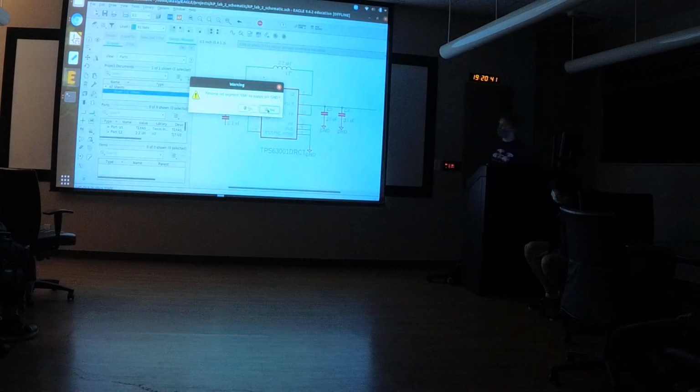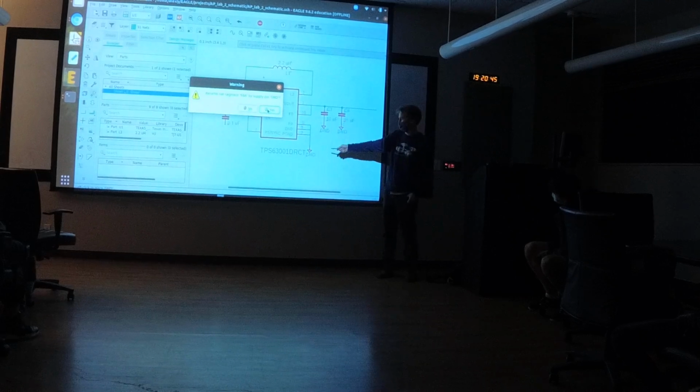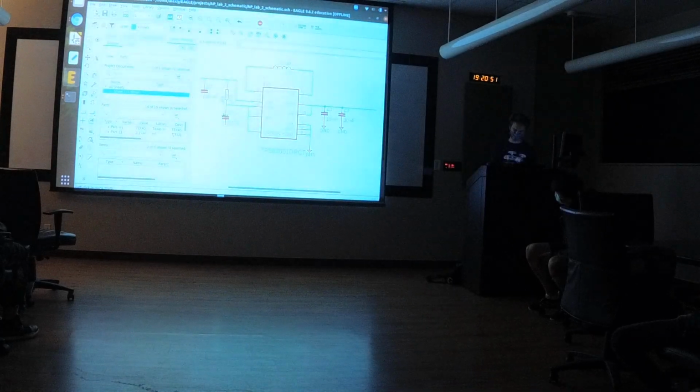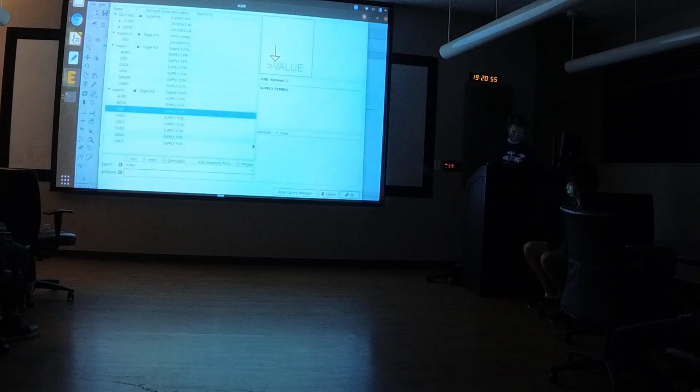It's going to ask you, do you want to rename this net segment N6 by supply pin ground? When you apply this, it applies a name to your net so that everything named ground will be connected to ground. We want this, so we're going to click yes. This is like a label that they give you because everyone uses ground.